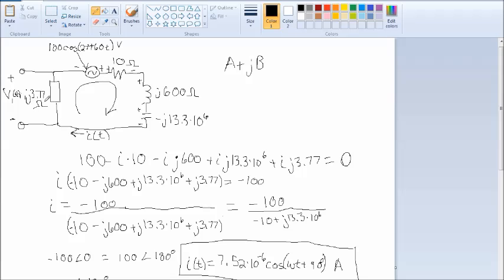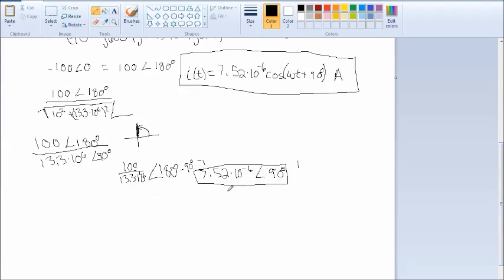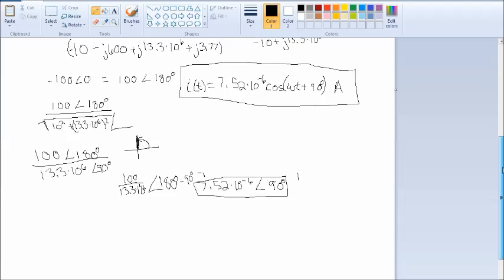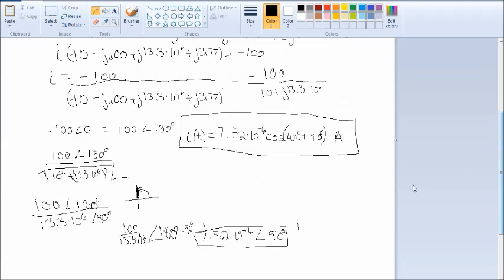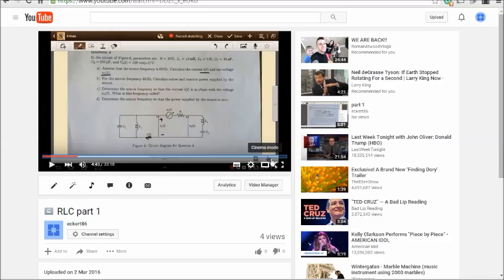So you're going to multiply this, angle 90 degrees, times this in polar form, times -1. Then you're going to use the same methods that we just used to bring it back into a time-dependent function for the voltage. So you should be able to handle that.